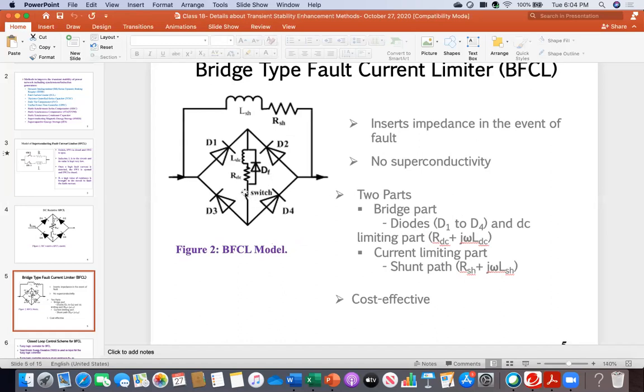This means when this line got disconnected, you have to consume that inductive energy, the stored energy, so that there is no sparking or other problem. So that's why current flows, and after a while, because no more current is coming, only this stored energy is consumed. After a while, it will decay, it will go away.